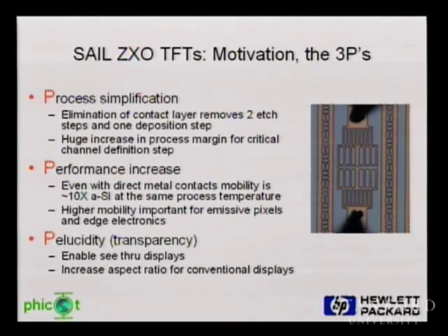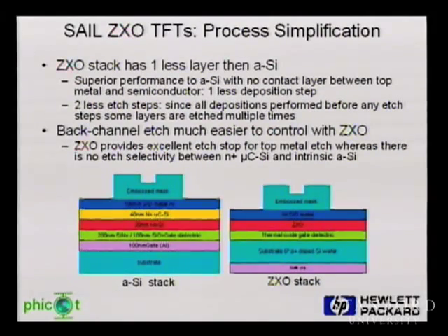And actually one of the big advantages from our perspective is that they simplify our process. Because when we do a patterning process, unlike in a conventional photolithography process where you pattern a layer once and you're done with it, we have all the layers to start with, so we have to pattern individual layers multiple times. So the more layers we have, the more etch steps, and it's a multiplicative effect. If we can get rid of one layer out of our stack, then we can save at least 3 or 4 process steps, which really has a big impact on the cost.